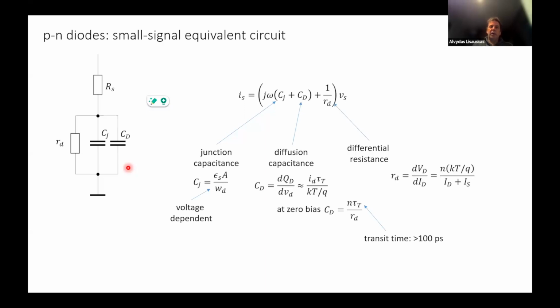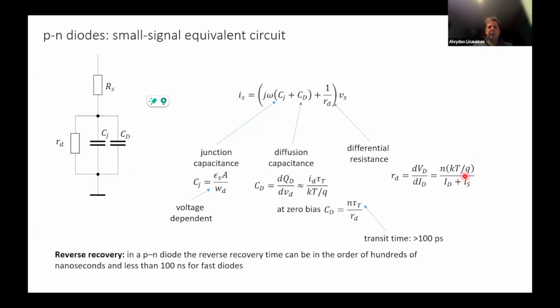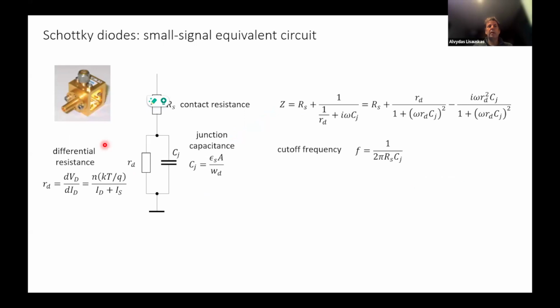Well, that's just the junction capacitance, and that's the diffusive capacitance directly. And there is a differential capacitance coming out of the IV characteristic. So we find out that PN diodes, just due to those two big capacitances, are not in general applicable at the terahertz frequency range. They are still very good, actually up to microwaves. But what is really exploited there is the Schottky diode.